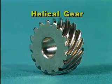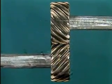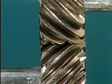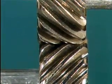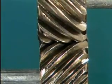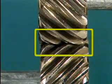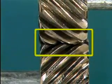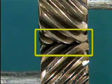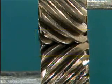a helical gear. As two helical gears mesh, the contact between the two gears begins at one end of a tooth and extends gradually across the width of the tooth. This allows the gears to run quieter and smoother. This is also true for the spiral bevel gear. If the face of a helical gear is wide enough, several teeth will be engaged at the same time. This multiple engagement of gear teeth allows a helical gear to carry a larger load across a single gear set.